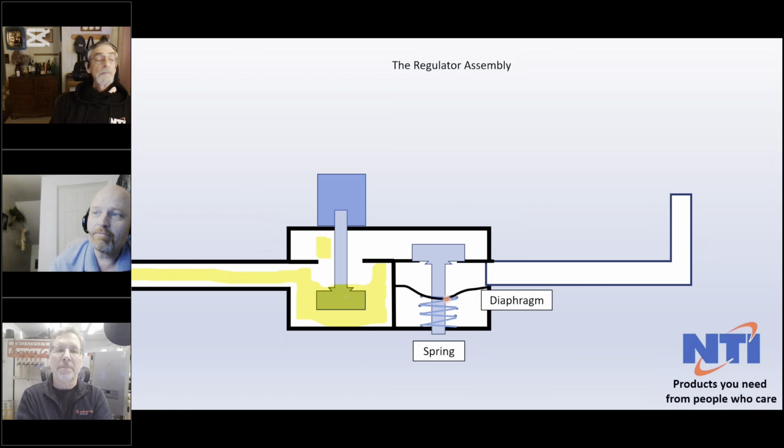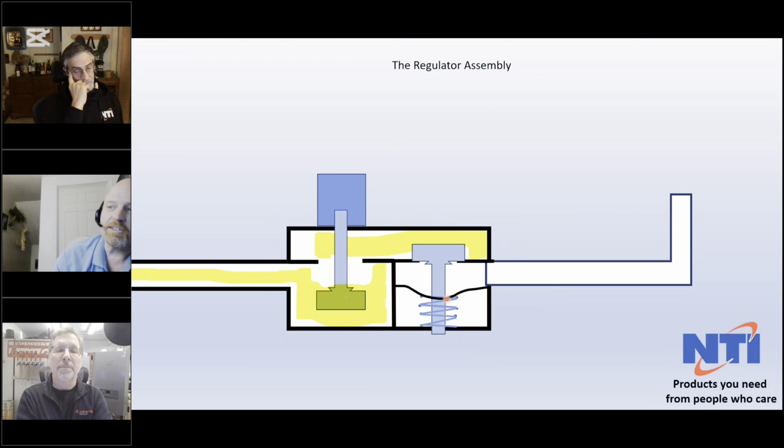Now what happens is when the solenoid opens, we allow gas into the valve, but in this particular scenario, the valve still isn't open. Gas is not passing through. There's nothing coming out of the outlet of the valve. So the question becomes, what opens the valve? Another part that is missing from this picture is this little vent adapter or vent regulator. What this does is provide a port to the outside world, or to the atmosphere. At least that's one thing that it can be used for.